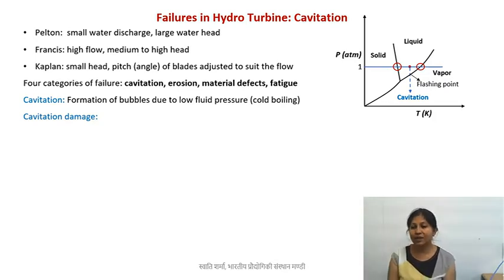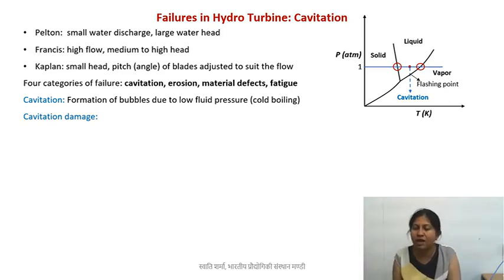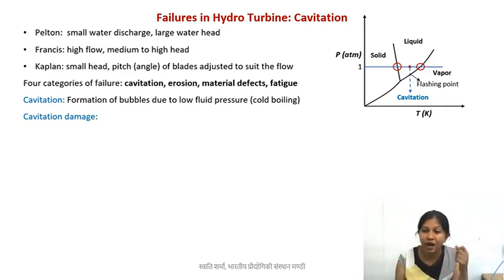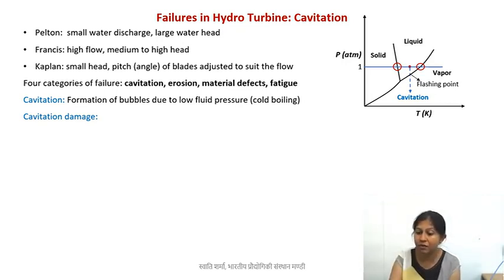So what can this cavitation do? So we understand that, okay, in the turbine systems, why do we have, by the way, lower pressure of the liquid? Because the velocity is high. So simple Bernoulli's principle: if the velocity increases, pressure decreases. So it is possible to have bubbles, and in fact you may have seen these vortexes of bubbles. Bubbles can even take different geometries. Near the edges or near the vortexes, the row of bubbles can have different geometries. But how can that damage your turbine, the material of your turbine?